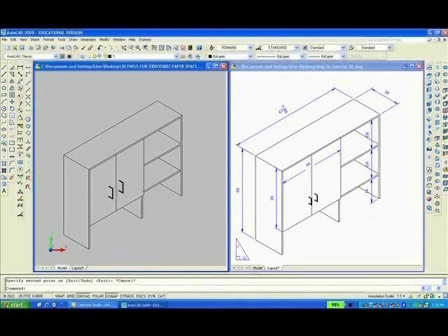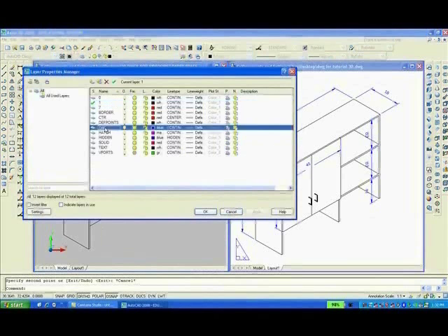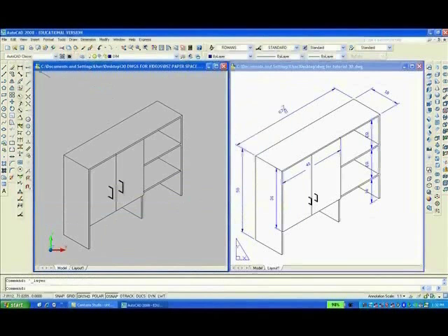Now, of course, we'll want to dimension the object, so we're going to change the current layer to DIM, and then we're going to put a dimension, a line dimension, from here to here. Why it came out wrong, I'm not sure, but I'll worry about it later. Oh, because I cut it to the nearest quarter inch, so don't worry about it. I should have made it to the nearest 1/8 inch. Sorry about that. This is good enough. All right, so we'll do it again.